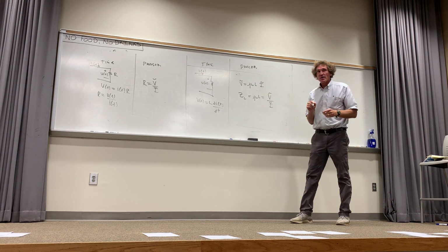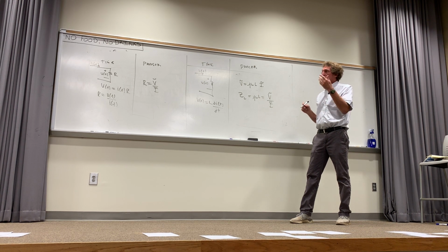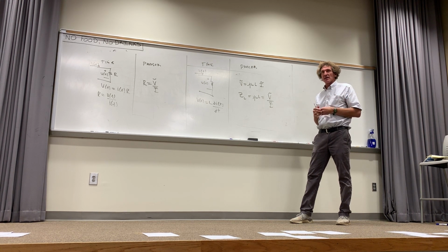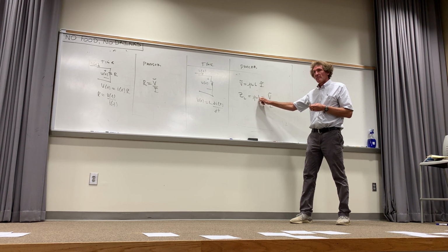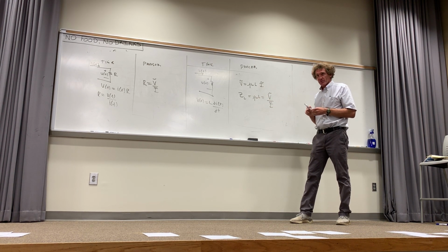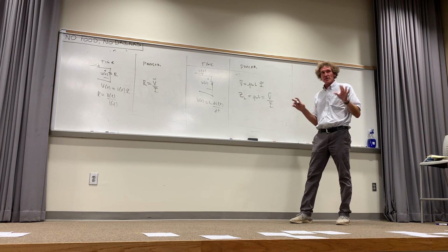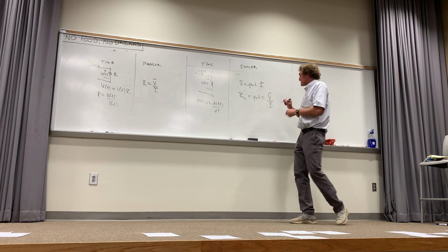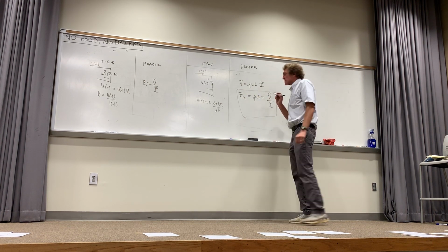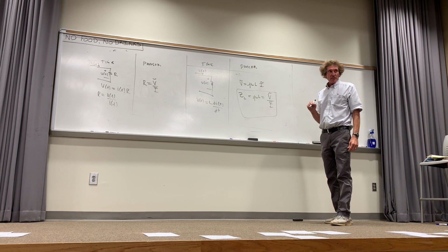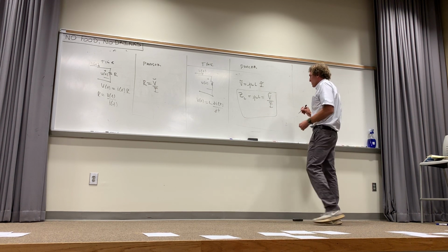Now this is very important. It's saying I can replace an inductor in a circuit that has a steady state drive, either cosine or sinusoidal varying voltage or current of a constant frequency, with just j omega L. Now omega is 2 pi times the frequency of operation. I'll do problems so this really gets beaten home to you, all right? So this is important. This is like the DC resistance that we've dealt with. It's a ratio of voltage to current.